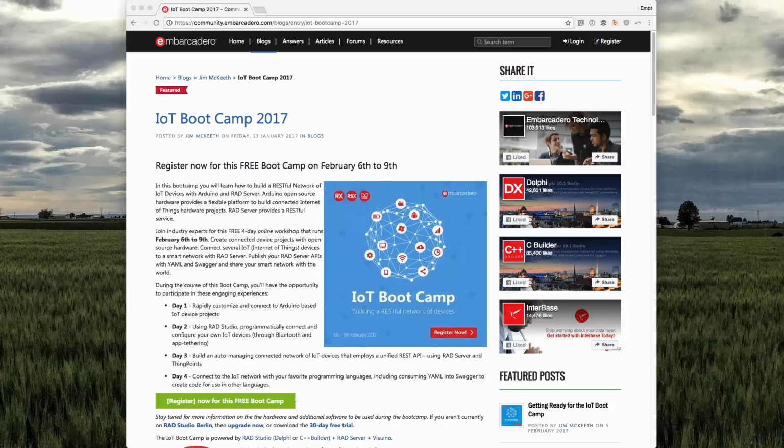The VIN pin, I have to look at the exact voltage range, but it is listed in the Arduino boards, something up to like 9 volts you can put on that pin. And the Arduino Nano has its own voltage regulator on the board, so it will convert it automatically to 5 volts and everything is going to work just fine. So yeah, you can power it with off-the-shelf battery.